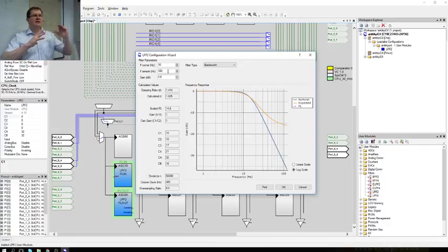Why am I using that much of the low pass filtering? Well, remember that our final sampling rate will be 2 times a second, which means the sampling rate for the final result was 2 hertz.